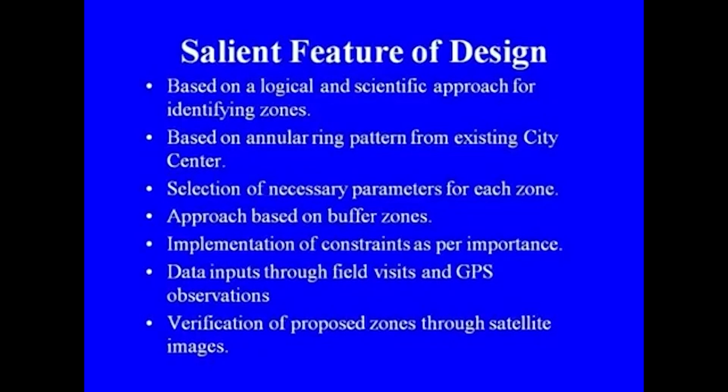Now, coming to the salient features of the proposed design, it is observed that it is based on a logical and scientific approach for identifying the zones. Specifically, when urban areas are to be developed, one of the very common techniques used is the annular ring pattern, and this has been adopted in this case. In identifying each zone, the necessary parameters in terms of minimum area and other connectivities and constraints have been taken into consideration.